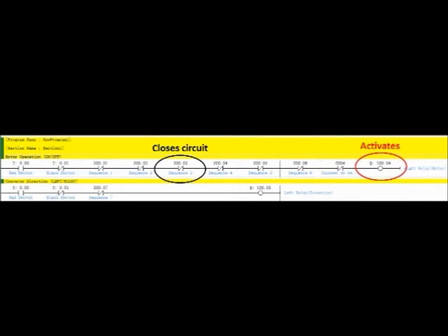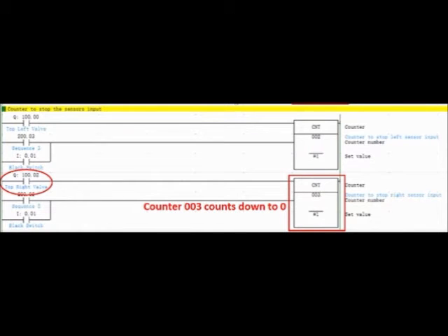The circuit for sequence 3 opens and sequence 3 is deactivated, leading to the top right valve retracting back to its original position. To prevent 2 balls from dropping instead of 1, again a counter is used at the same time the top right valve is activated. This ensures that a second ball from the right tube will not fall in between the space of the top right valve and the bottom right valve.